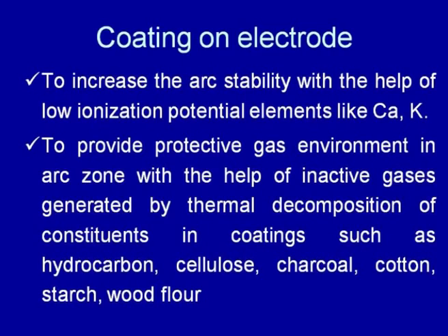Further, to provide the protective gas environment in the arc zone with the help of inactive gases which are generated by thermal decomposition of the micro constituents in the coatings, such as the hydrocarbons, cellulose, charcoal, cotton, starch, wood flour, etc. These are the constituents which are added in the form of the coating materials.